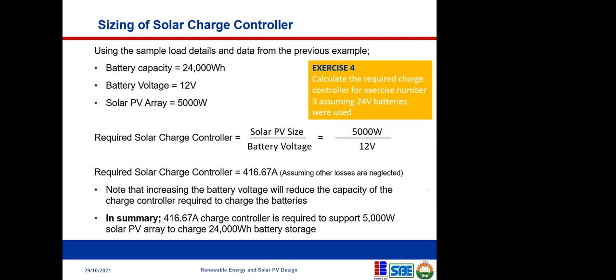You're very correct. So these are the things you look at in your design, right? Remember I talked about parameters you can adjust. If it's very impracticable to have this, you can begin to tinker with your design, your voltage. You can consider the voltage you're using for your system, which will automatically change the charge controller size you need.